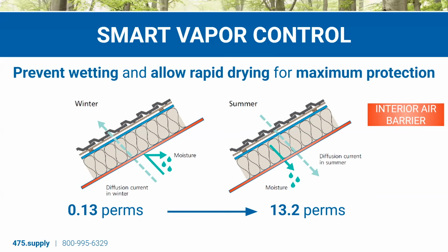If there is a moisture buildup, if there's a high relative humidity buildup around this membrane, it will become vapor open. So because it will never trap moisture, it's why we're comfortable using it in more humid climates on the inside. Even when the vapor drive's coming from the outside in, we might very rarely want it to be a class 2 vapor retarder in these climate zones 2A or 3A, but it won't do any harm. And in fact, just having that interior air barrier is quite helpful.